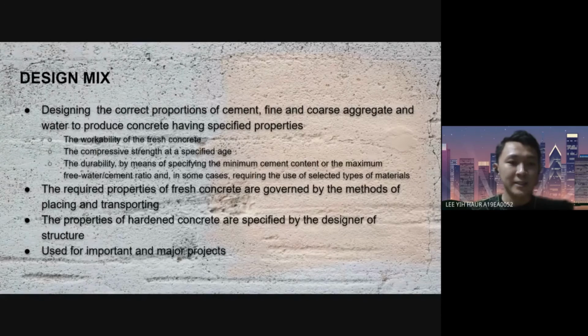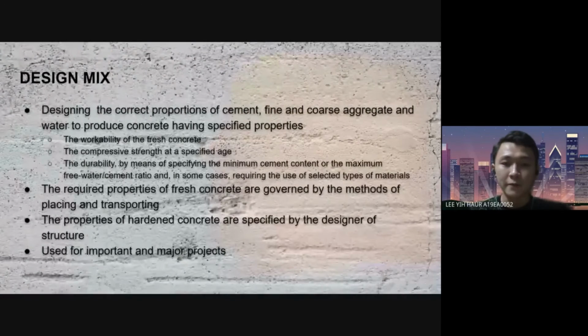Okay, thank you, Dayao. The design mix is designing the correct proportion of ingredients, which are the cement, fine and coarse aggregate, and water, to produce concrete having the specified properties. These properties are usually the workability of the fresh concrete, the compressive strength, and the durability.